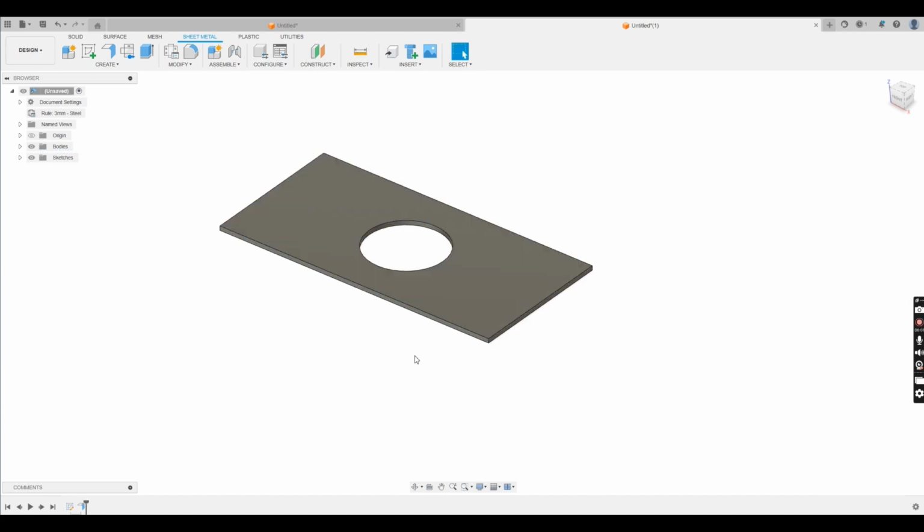Let's just say, for example, we wanted to change that 3mm down to 2mm. On our left here we've got a rule. So instead of going back and redoing what we did, the 3mm rule is set here. So we can change that by hitting this button here, switch the rule, and for example if I wanted to go to 2mm, hit OK, notice the material actually decreased down to the 2mm rule. So that's a need to know.